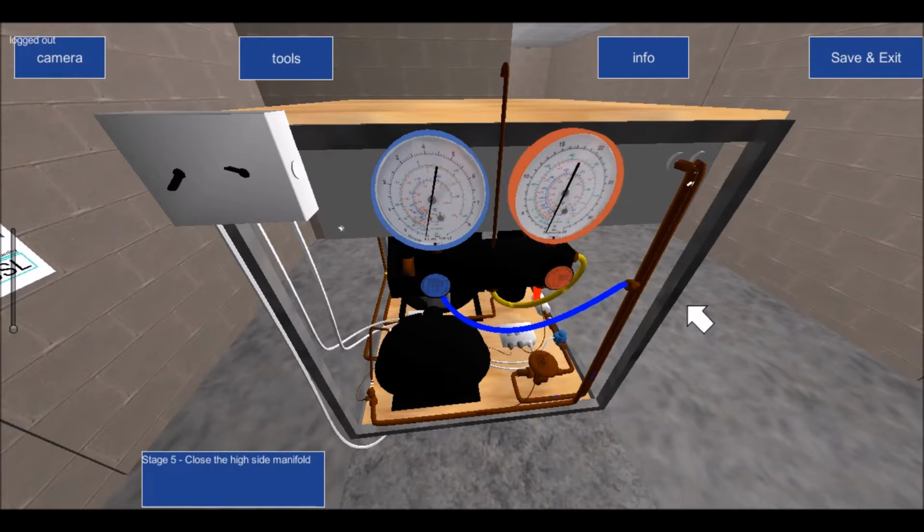So all you will find in your system is that the stat energizes and de-energizes the compressor. So during normal operation, the compressor will stop via the thermostat, and the pressure switch only comes into effect when there is no gas in the system and acting as a safety device.